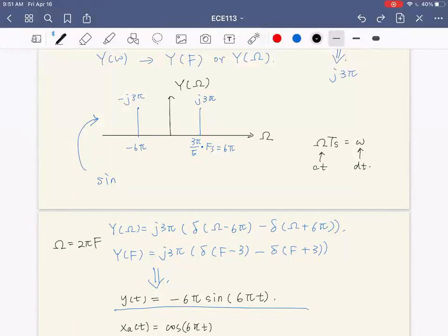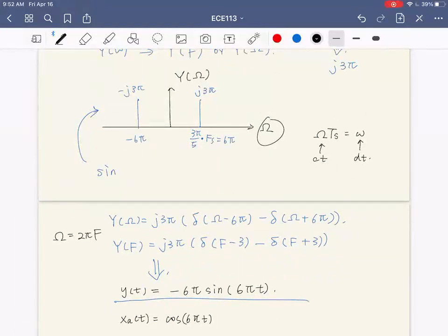So if you're doing the equations of CTFT, you can feel free to change your variable from omega to f, and it will not change your magnitude. The only difference is when you try to recover y of t in terms of something times the big Y of omega or the Y of f. In this case, it would generate a multiple of 2 pi. So switching between Y of f and omega is fine because it is only changing the horizontal axis.